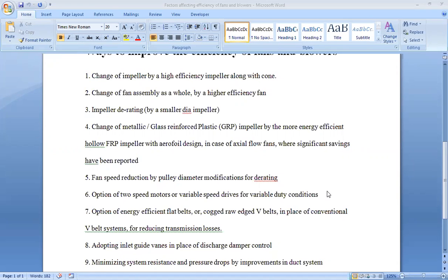Or we can change that duty cycle. For example, we can switch on the fan for 2 minutes and switch off the fan for 1 minute by a software program, and it will be automatic switching of the fan. For 2 minutes the fan will be switched on, for the rest of the 1 minute the fan will be switched off, and again for 2 minutes the fan will be switched on.